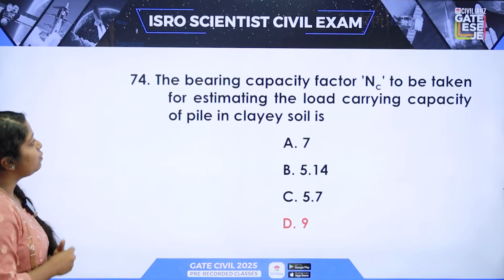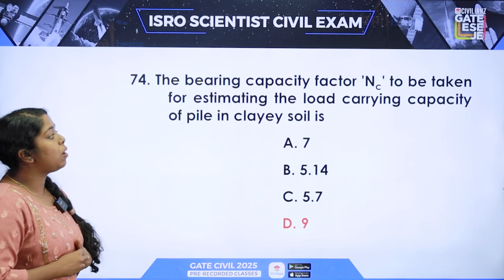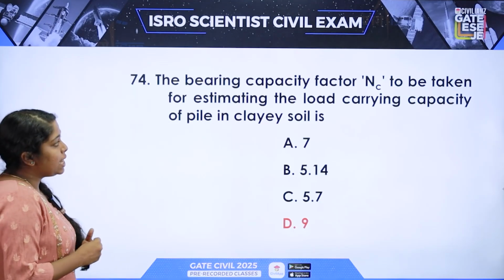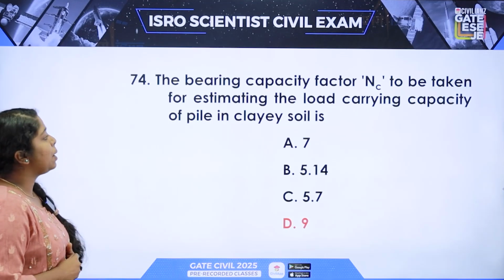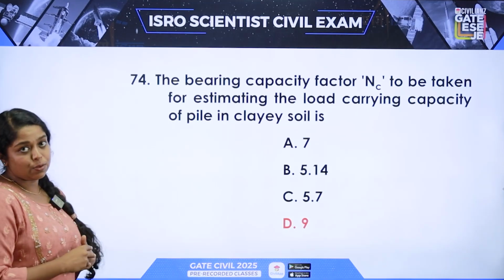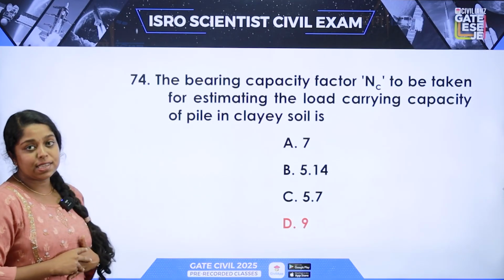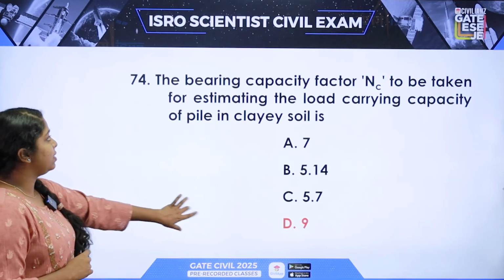Moving on to the 74th question, this is about the bearing capacity of soil. It is again a question from foundation engineering. So, the bearing capacity factor Nc, what value of Nc should be taken for estimating the load carrying capacity of a pile in clay soil. So in the case of clay soil, the value of Nc is usually taken as 9. So option D is the right answer.